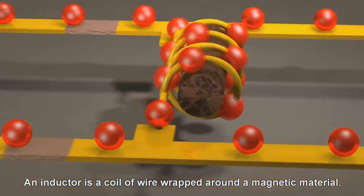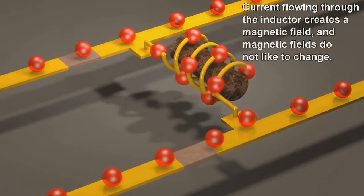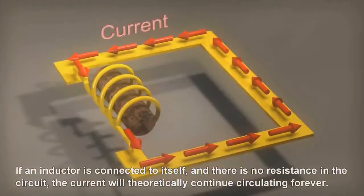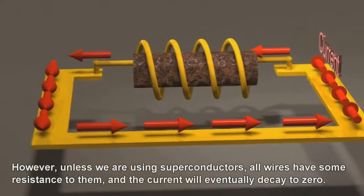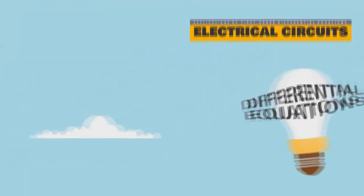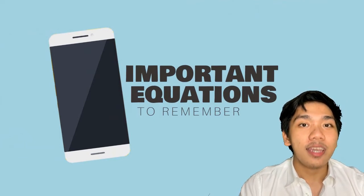A simple closed electric circuit is one in which a resistance R and an inductance L or a capacitance C are connected in series with a source of electromotive force, or EMF, of E volts. The differential equation necessary to solve the various problems relative to this circuit is derived with the use of Ohm's and Kirchhoff's laws. The following are important equations that signify the relationship of each variable in a given circuit.